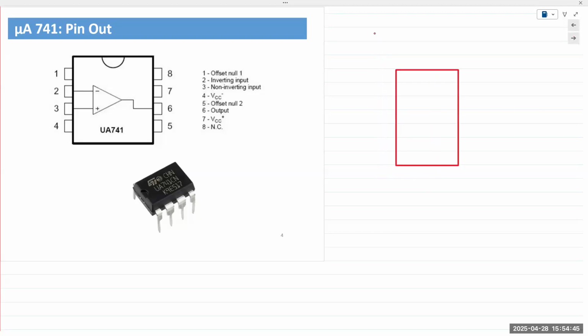Okay, rectangular chip, black epoxy packaging, right? We don't want it getting affected by any external light sources or any external energy. And there is a notch at one end or a dot. Okay, what does the dot or the notch indicate? For those of you who have used it in the lab, pin number 1. So the notch indicates pin number 1.